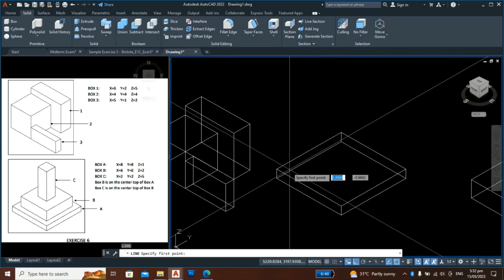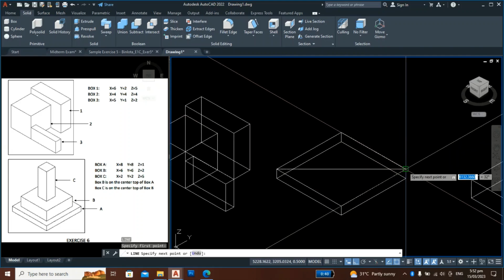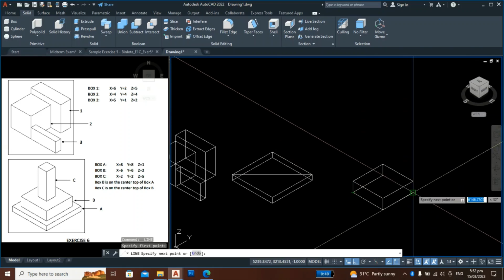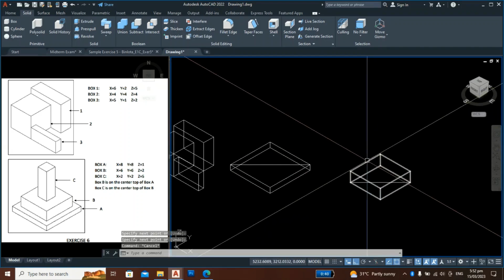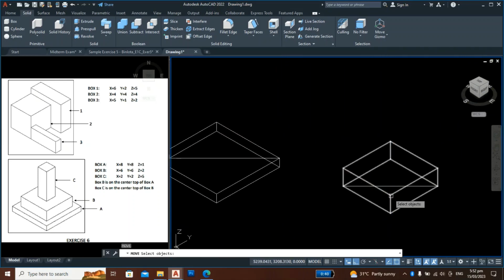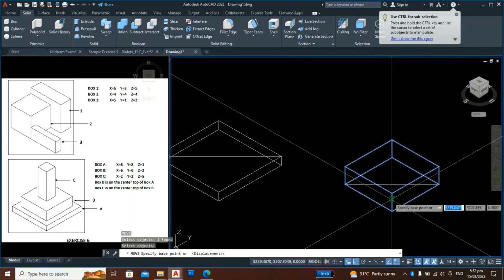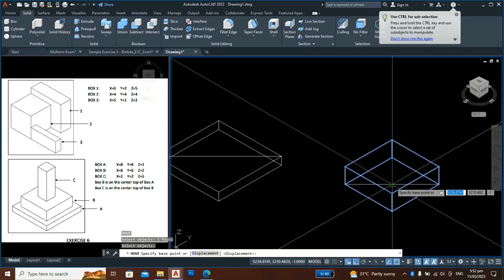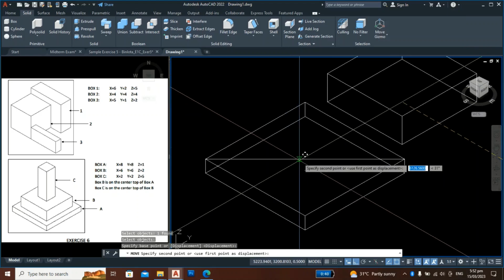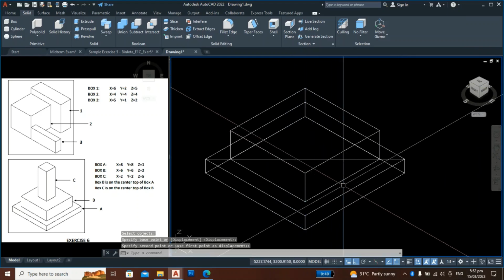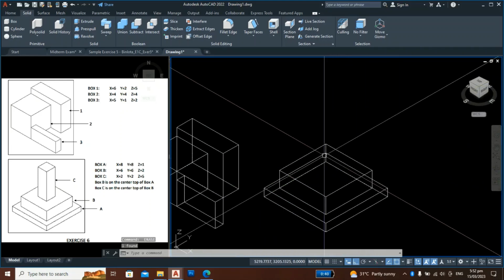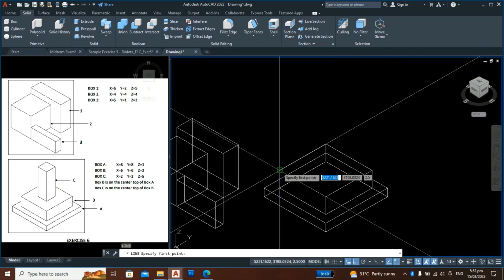Okay. So meaning we have to use now a reference guide line. So click here, draw a line, and also here draw a line, in the bottom for the second box. For the first box, the same. Then move this box, but your base point is the midpoint of this line. So here, click this and click the midpoint also of this line. Click. Okay. Then erase this. You already used that, and also erase this. Then draw again a line here on top. Okay.